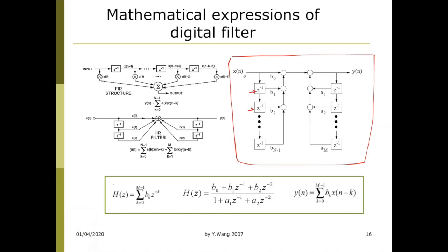For example, in this case, the signal xn comes in, and this is the output yn coming out. The signal comes in, goes to a delay, and the coefficients are applied, and the signal yn goes to a delay line. Those squares with z minus 1 are delays, and the coefficients of the output signal are applied and summed to a new output signal, such as that.